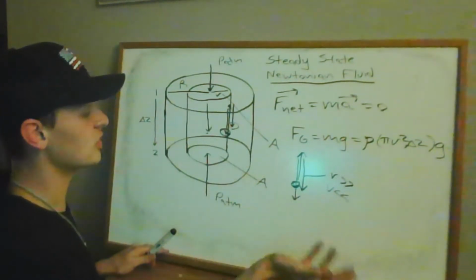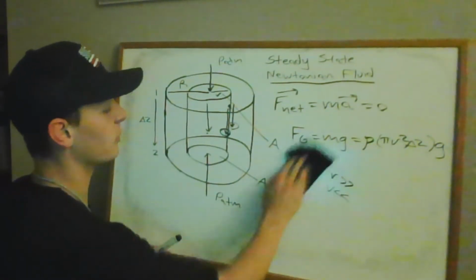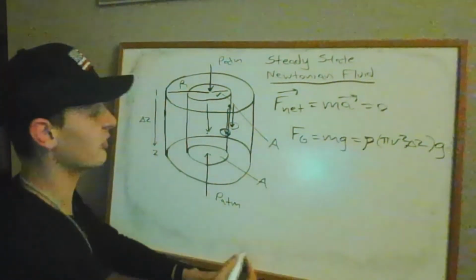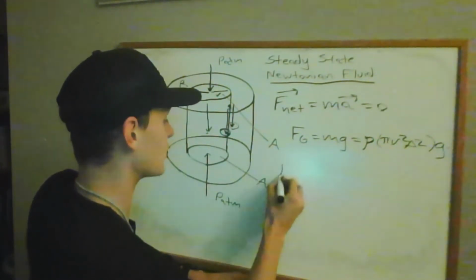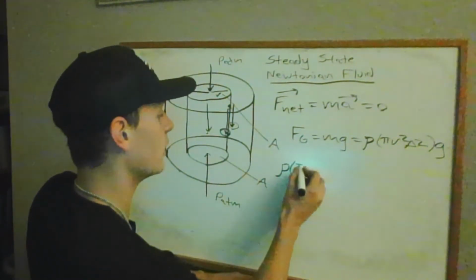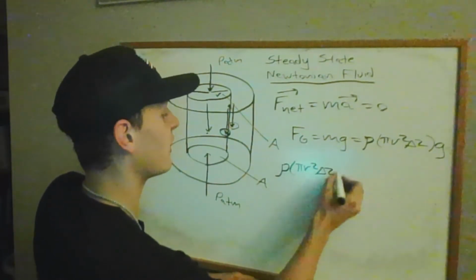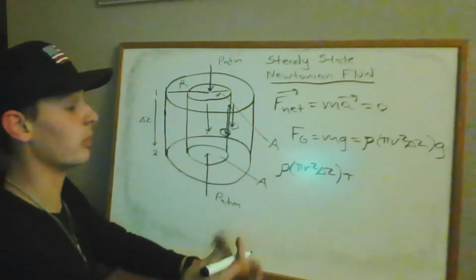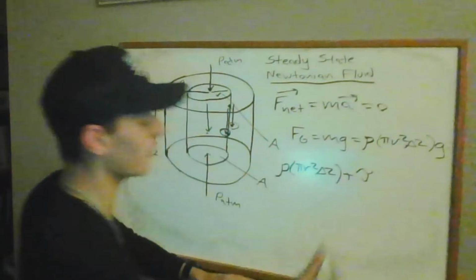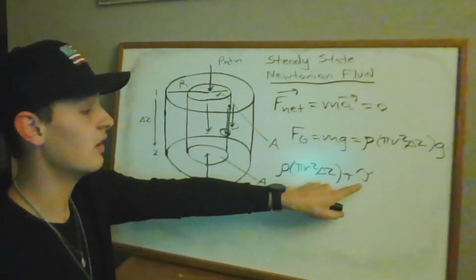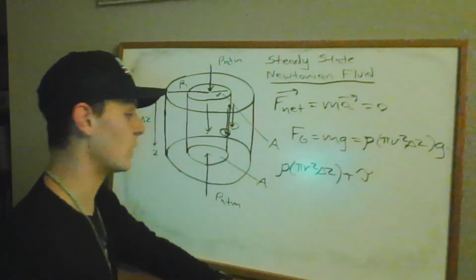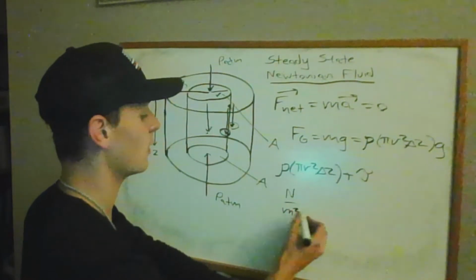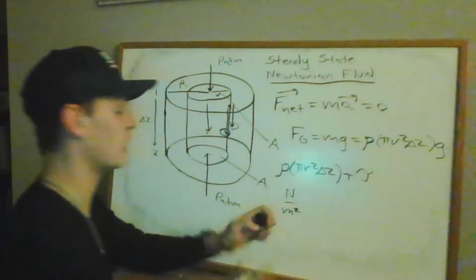Well, that means that this shear stress has to be added on, specifically, of course, the force, because we're performing a force balance, okay? And again, we know that our net force is equal to 0. So we already have this expression for the weight of our fluid. We just have to consider how we would express the force due to the shear stress that's exerted by the fluid on itself, right? And I already revealed this, didn't I? Because we have tau, that's the shear stress itself, okay? Which, hopefully you remember, would be in units of Newtons per meter squared.